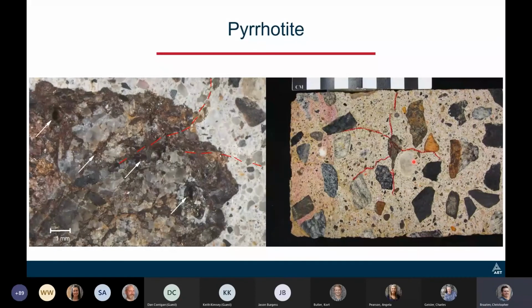They did several studies on it, and they concluded that it was this pyrrhotite mineral. And they actually did enough background research to figure out that the pyrrhotite belonged to one aggregate produced at one quarry. I'm not saying anything that isn't public information right now, but they traced it back to one quarry, and I believe it was a metamorphic rock, a gneiss particle, or a gneiss lithology, and it had a lot of pyrrhotite in there, and it created this path of destruction, I guess, out there.